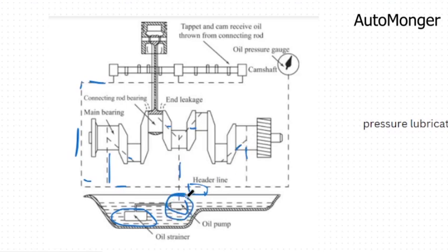So because the pressure is high, it can get to all those points and lubricate all the bearings perfectly without any issue. So this system is very, very effective because whether you are running at a high speed or a low speed, it doesn't matter. As long as the pump is on, the whole system is lubricated, and it ensures that your bearings and all the parts last longer because they are always lubricated. The connecting rod everywhere gets oil, the piston wall everywhere gets the oil. So once the oil finishes doing its job, after going through the points, they all fall back, like the normal system, by gravity, to the oil sump.